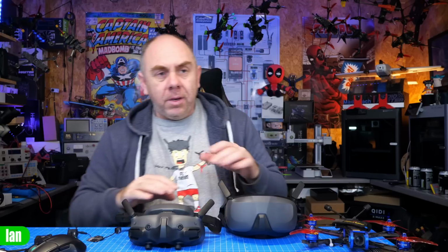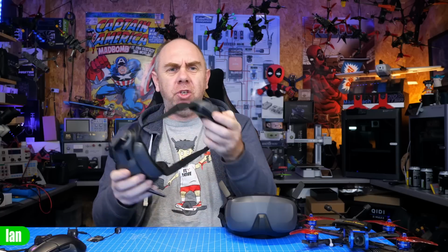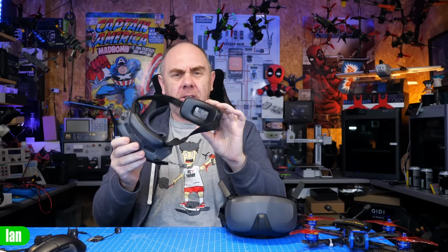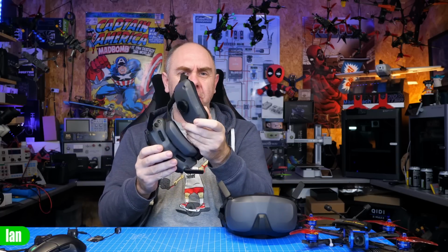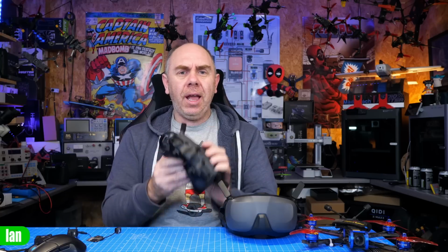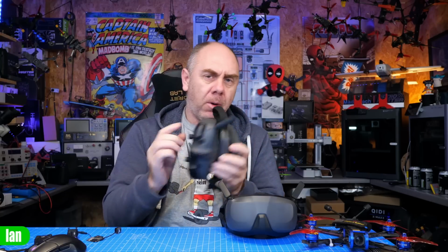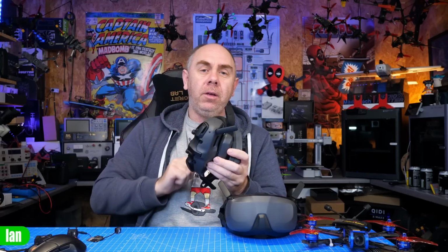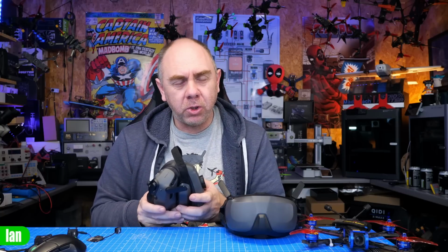Now, with regards to using the DJI Spectator mode, you can absolutely use that between these goggles. Unfortunately, though, you cannot spectate to an older set of goggles, even in race mode. You would have to be using Goggles 3 or Goggles N3. Now, one other thing quickly to mention on goggles is battery, because one of the big limitations pilots may have for this is, I don't like this, I want to use an external battery. Now, you can use these goggles whilst powering them off USB. However, you can't do that if you're using Cosmos Streamer.